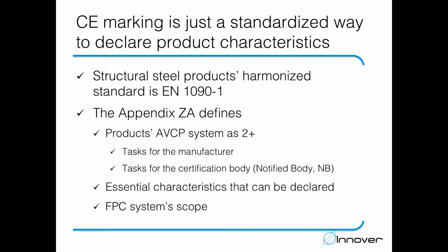And then we saw that in order to have enough proof to back up, for example, weldability or fracture toughness, or even durability, we are going to have enough proof, and this proof basically translates into having a documented manufacturing process. And in this case, not just any manufacturing process, but the manufacturing process that is built according to EN 1090-2, that actually is the twin of this 1090-1, and which deals exclusively with the manufacturing and also with the erection of structural steel products.